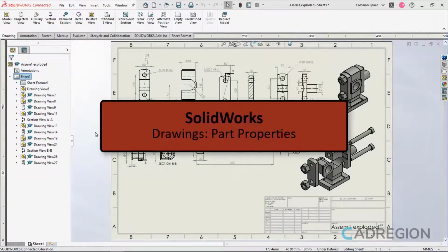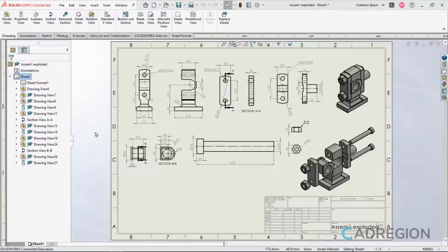Before you insert bubbles with numbers to number the parts and tables with the parts properties, you have to specify those properties in the parts document. So, in the open document, I have placed all the necessary part views of the assembly as well as the necessary assembly views on the paper. In addition, I have added dimensions. However, I have not specified their properties.